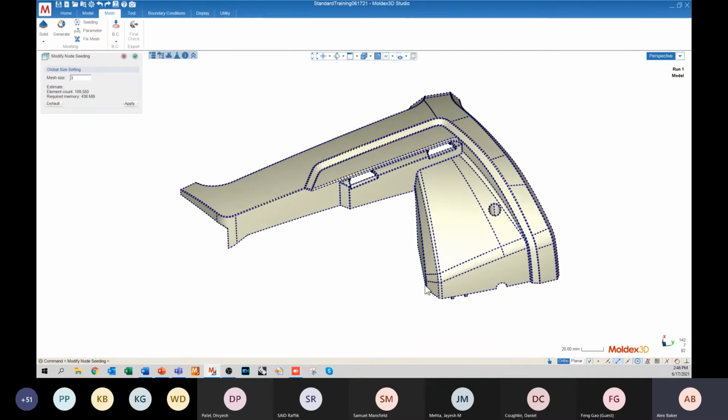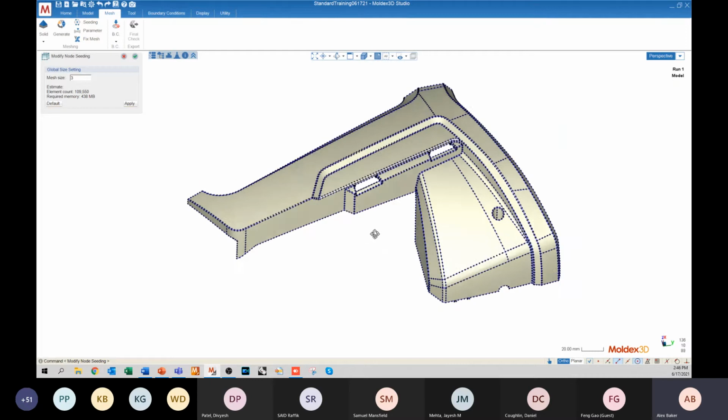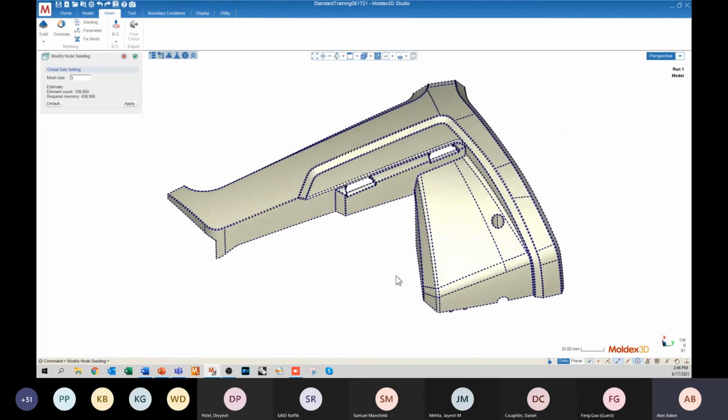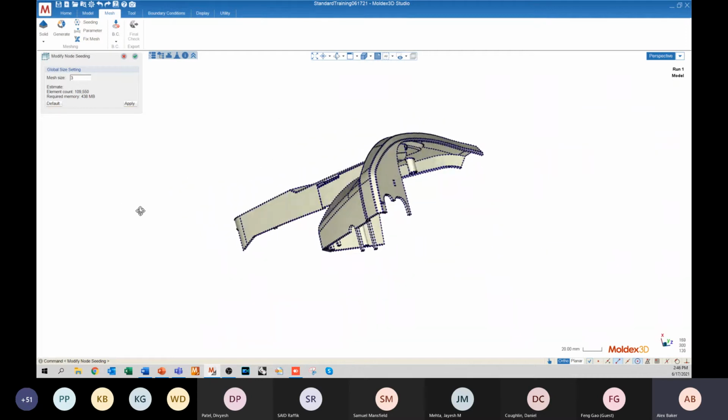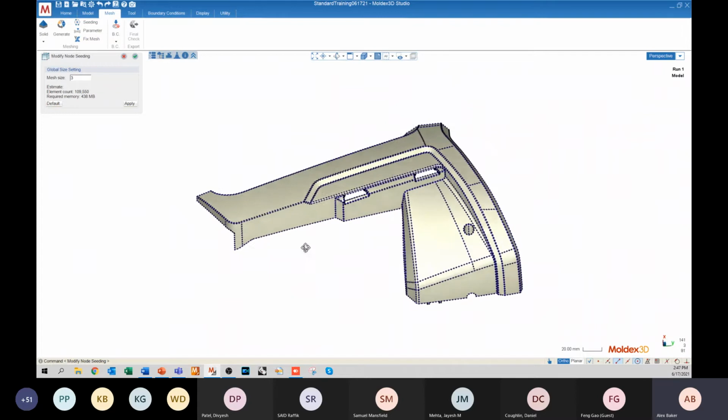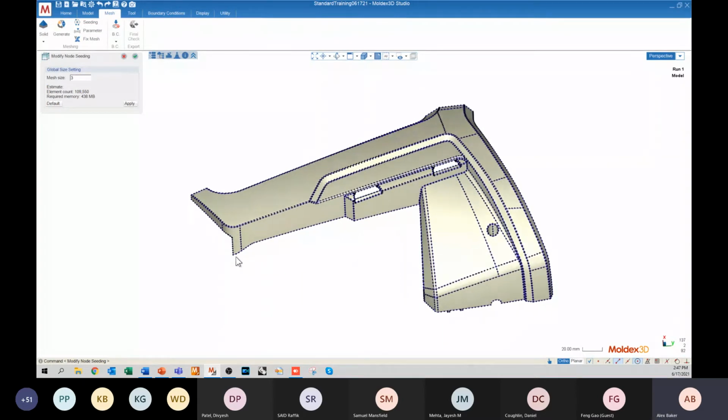If I were to mesh just a box with only 6 surfaces, that only gives me 12 feature lines to go off of. And those 12 feature lines are not really enough to give me a good definition of mesh size, right? I need a good number of data points in order to achieve a reasonable mesh size. All right, so it's just something to keep in mind.